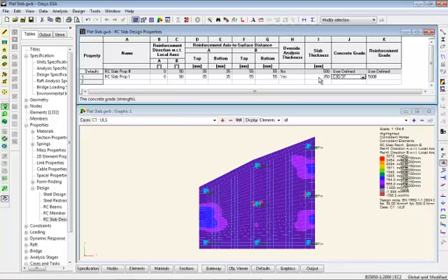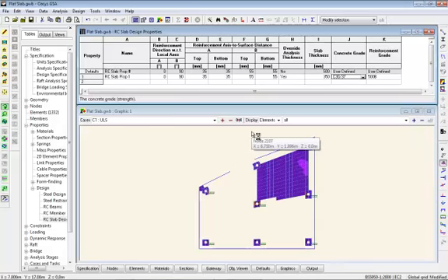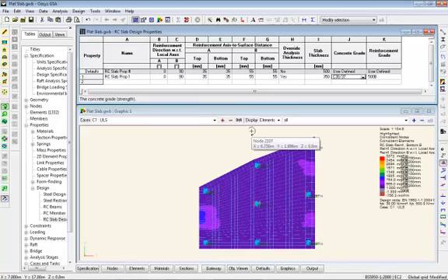But I'll just type in a 350 thick slab, so increase up to 50 mil, and let's see what difference it makes to the reinforcement. And you see it has reduced those areas of additional bars, but maybe not enough. Let's just try a 400.